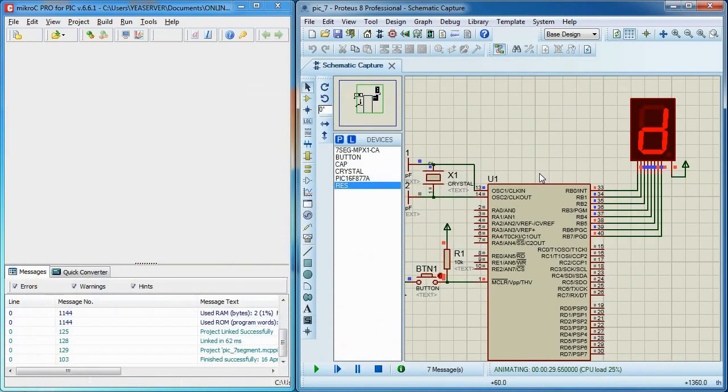Good luck. For the next example, I will show you the alternative, how to connect the 7 segment to the microcontroller. In this circuit, the 7 segment is connected to the microcontroller through port B. There are 8 wires here, and this might give a problem if your project consists of multiple 7 segments. You might not have enough input-output ports at the microcontroller side.